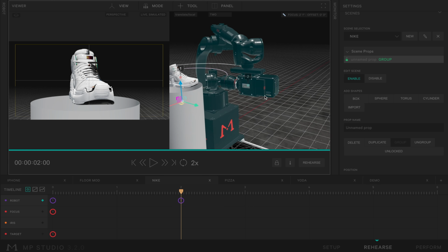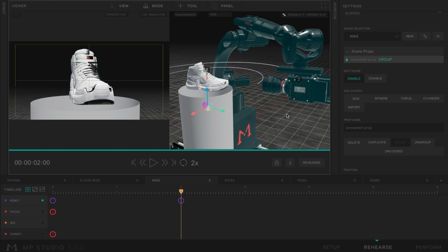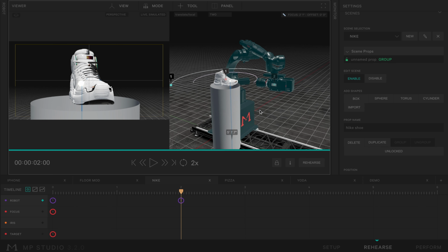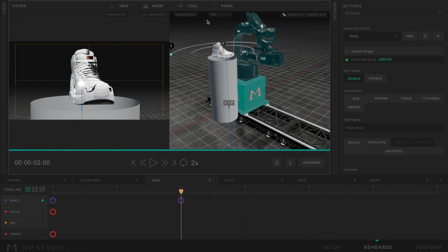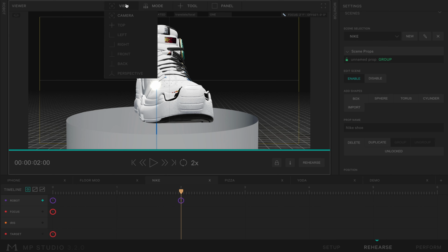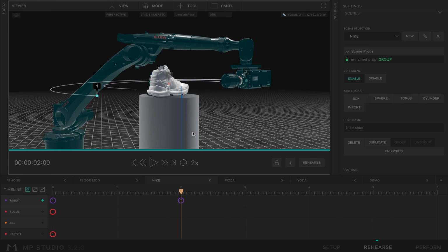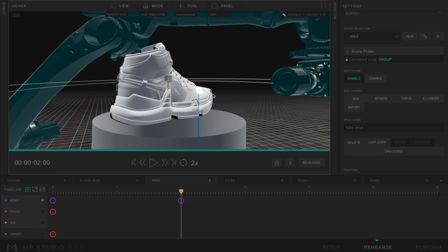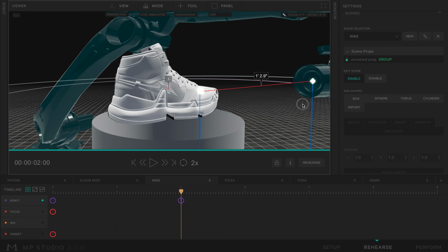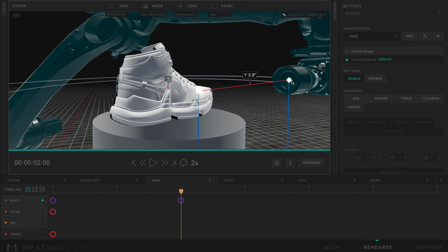So the next thing I want to show you is the measure tool. If you hold Option and click, it will measure from the ground. Here, I'll go to 1-up for a moment. Change the perspective. It will measure from the ground to the object, wherever you clicked. If you hit Option, click again, you can then make another line to, like, let's say the front of the camera. If you just hold down Option, you have a transform tool so you can drag these things around.